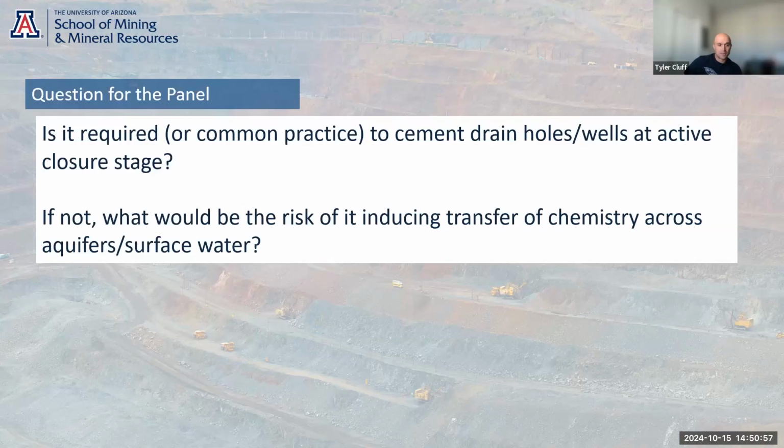Yeah, and just, sorry, go ahead. I was just going to say, from a practical point of view, realistically, you can't cement up drain holes, right? They're up on the benches you can't access. You're not going to get access to even the drains on the lower benches to drain them, and then the consequences, right? The drains are there for a reason, to maintain pit stability, and it's incongruous really to grout them up while there's still activities happening in the floor of the pit on closure.